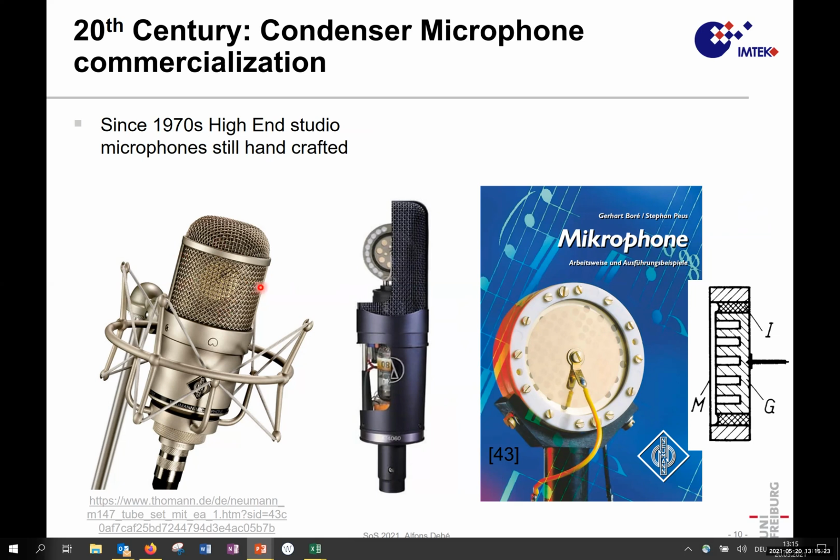That is basically the diaphragm that is inside the system. If you open such a housing, you have a vacuum tube below, and it's still amplifying the signal and biasing the diaphragm. Those high-end microphones have very, very good signal-to-noise ratio, so they're high-quality devices.